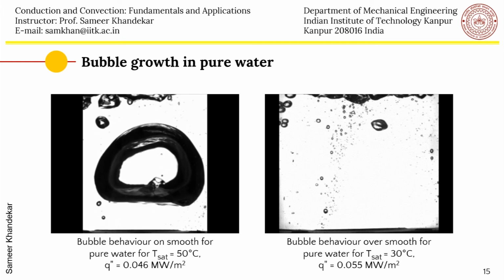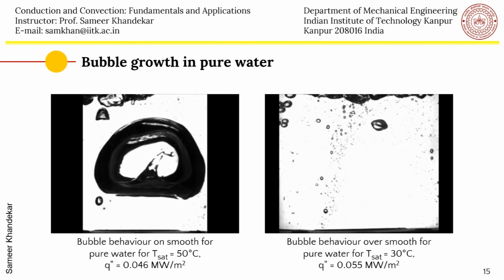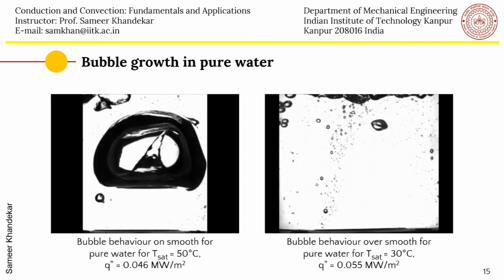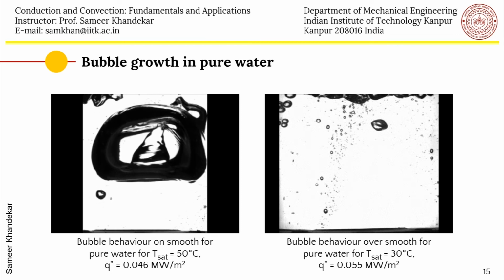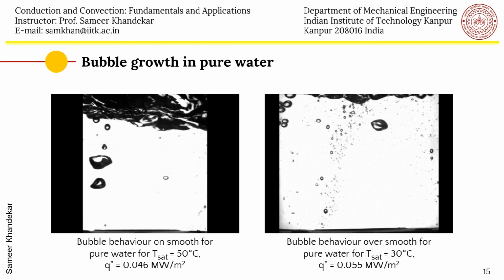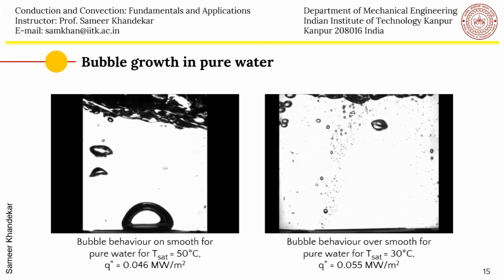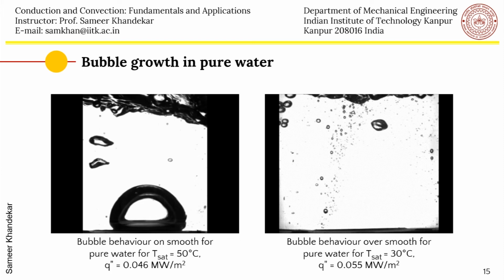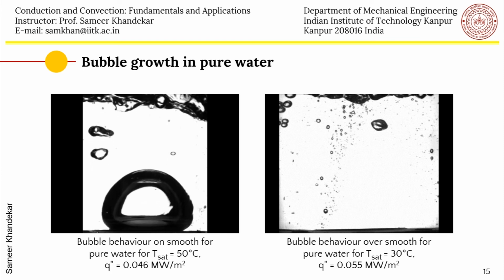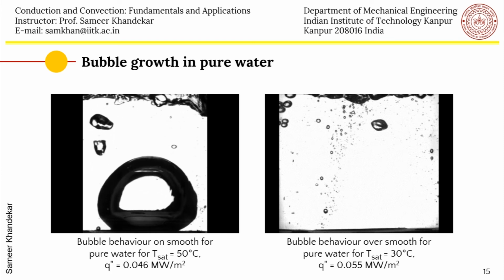How does it grow? You can also see the contact angle of the bubble on the surface, and you can see some surface ripples, and now the necking starts, and now the bubble departs, and as it departs, because of the fluid mechanics behind the wake of the bubble, there is a reflux which you can see, and the bubble now goes away from the surface.